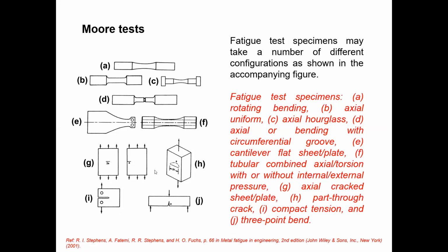So we can find out the crack growth time period. If you want to find out the crack growth fatigue lifetime, this is a partial lifetime of the fatigue life. If you want to find out the total fatigue time, that means crack initiation, propagation and growth and everything, you account with this kind of shape of specimen.